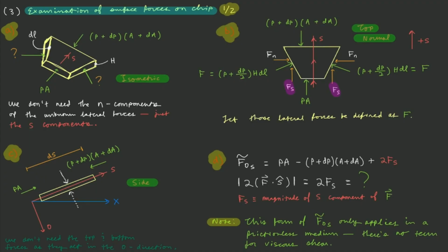And you will see that in many areas of flows, friction is incredibly important, like in low Reynolds number flows, like in boundary layers, etc. So Bernoulli's equation will not apply and will not give you the correct result when you can't neglect friction, because Bernoulli's equation is, as you see here, completely neglecting friction. It's not accounting for those forces that would be on these faces that you would need to account for in the S force balance.